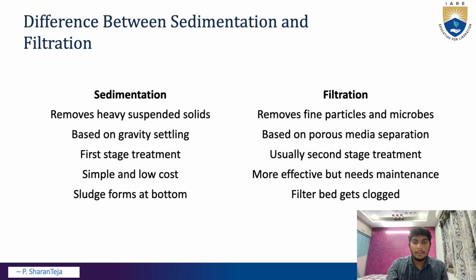And the difference between sedimentation and filtration. Sedimentation uses gravity, removes heavy particles, is slow in process, is the first stage, and produces less cloudy water. Filtration uses filter media, removes fine particles, is a faster process, is the second stage, and produces clean water.